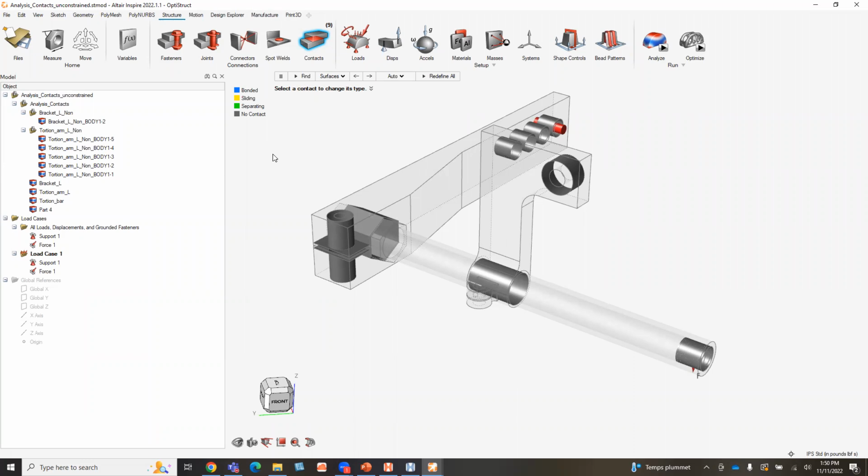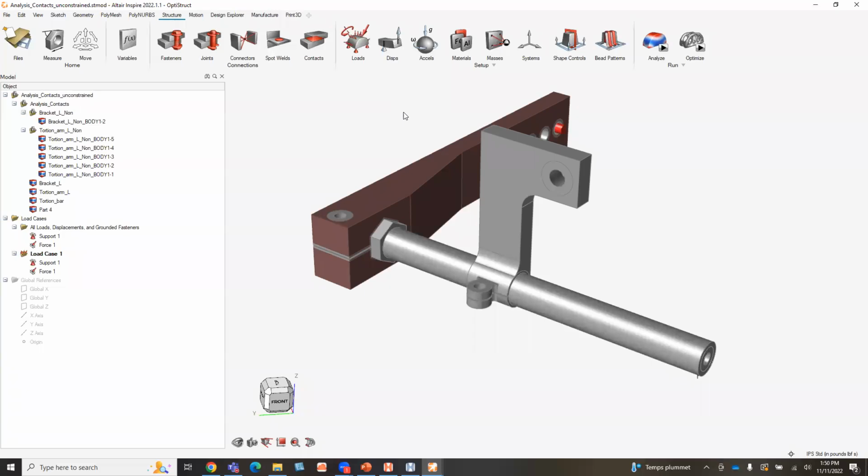One of the things I was taught early on in my career was that when you start dealing with assemblies, it's hard to probe every single one of your connections. Obviously, this one's simple, but with a larger system, one of the things we know from theory is the idea of rigid body modes. With natural frequency, you can determine if your system is constrained properly by rigid body mode theory. Meaning, if you run a natural frequency case and within those first 6 modes you have a resonant frequency that is not a zero-based value, then the system is constrained. I'll show this to you. If you've never run resonant frequency, this might be a game changer.